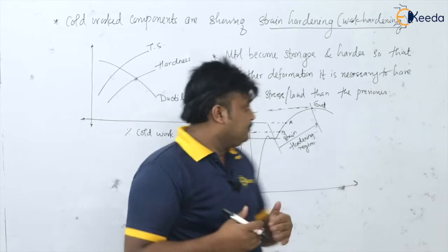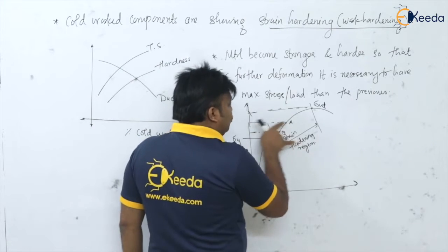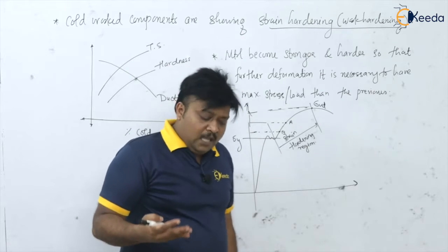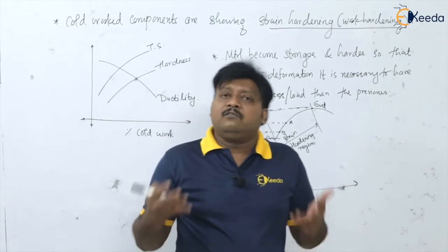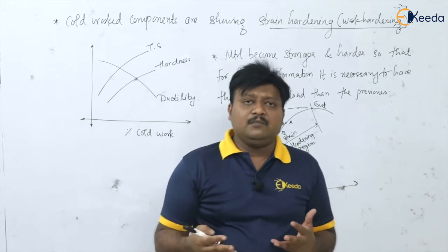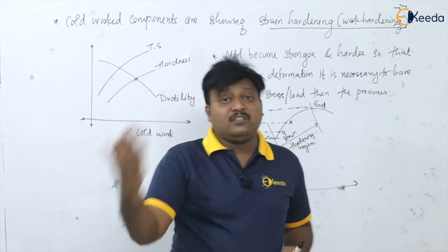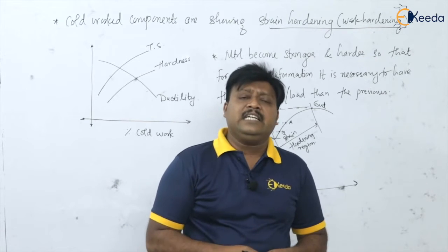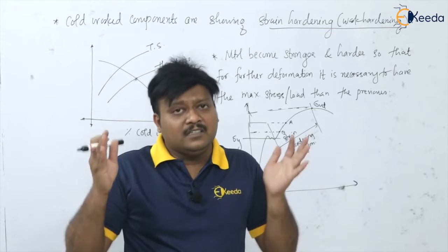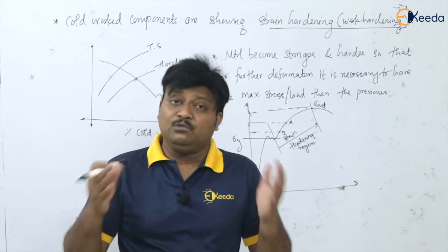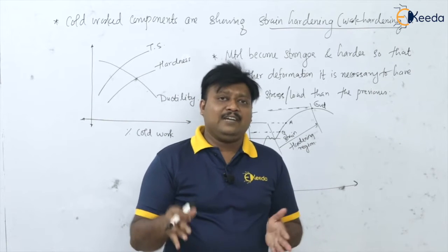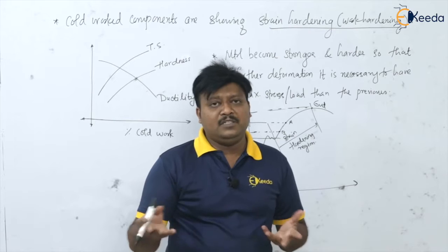Okay, and in such a situation, if you go on working on the material, definitely up to a certain limit, no doubt we will have the deformation even in this strain hardening region. But after some time, when we cross the limit of deformation, definitely there are huge chances of crack occurrence, the crack formation in the workpiece. So that is very hazardous. If a crack forms, definitely the component has failed.